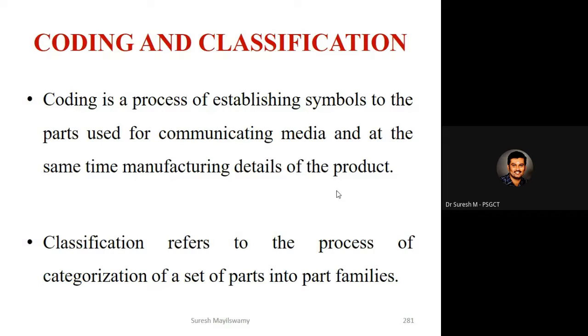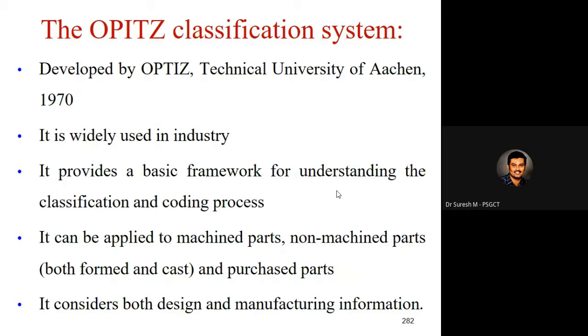And coding and classification, considering group technology, is the important thing. How to classify the part family is called coding. So here the Opitz classification system was developed in Germany and is widely used in industry, and it provides a basic framework for understanding the classification and coding process.